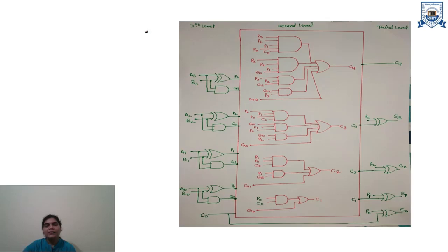Here we have the detailed design of the carry look-ahead adder. As soon as the inputs are given, the Pi and Gi values are calculated. In the second level, a carry look-ahead generator circuit is used to calculate the carries.